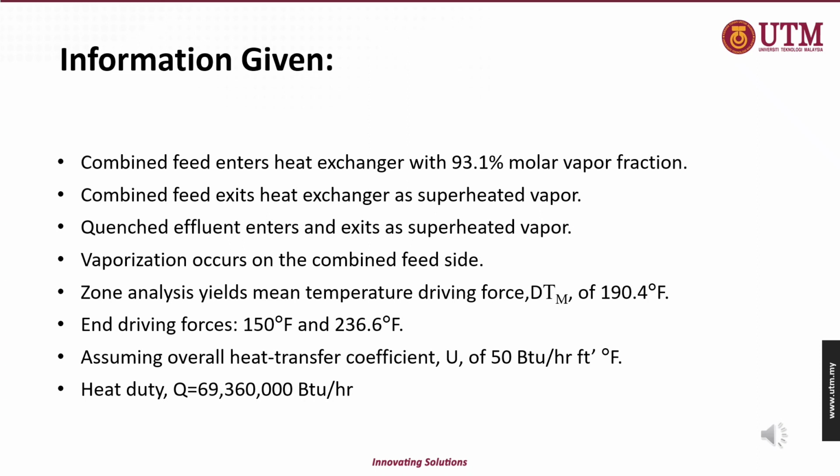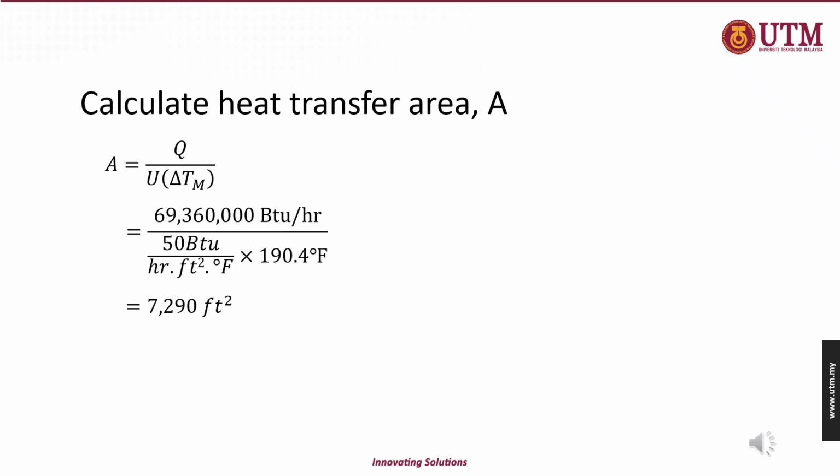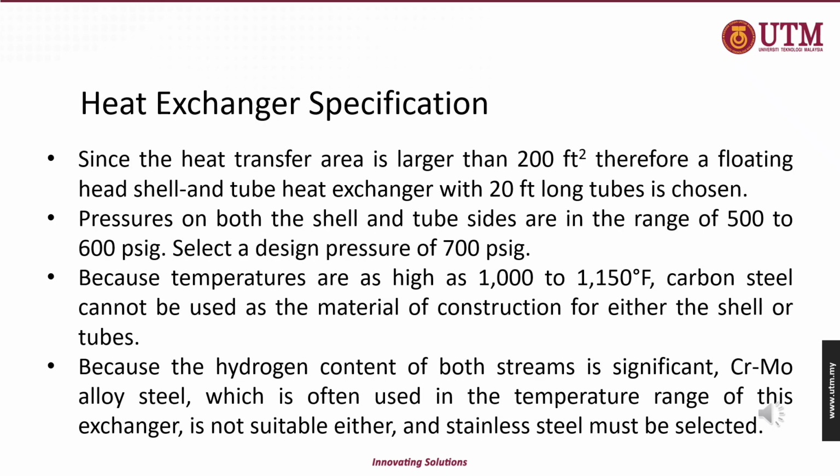and the last one is heat duty Q equal to 69,360,000 BTU per hour. To calculate heat transfer area, A equals Q divided by U multiplied by delta Tm. The answer is 7,290 square feet.